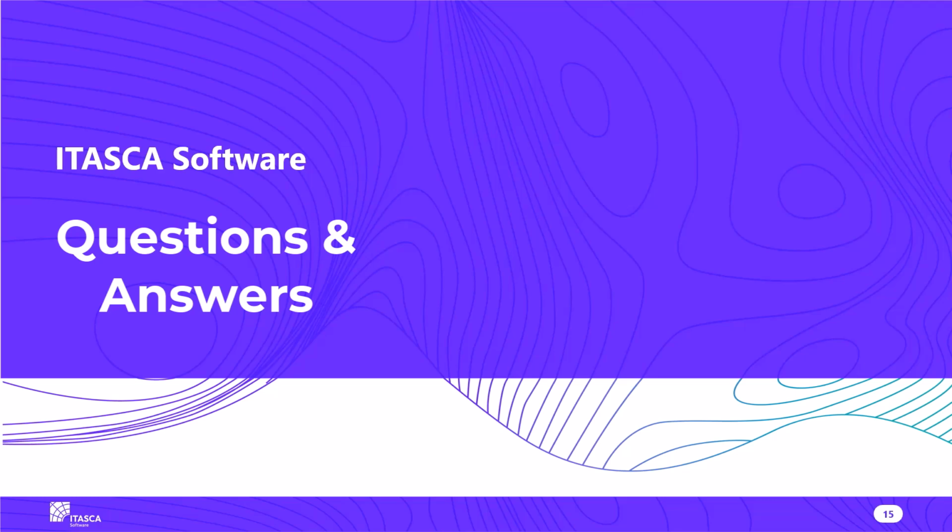I'll take that one. Hoek-Brown does not have to be perfectly plastic. You can have hardening, you can have softening. 50% of that question we can do. It's already built in to allow hardening and softening. In terms of viscoplastic, assuming you mean time-dependent creep type stuff, that is not built in for the Hoek-Brown model. We do have a bunch of different creep models that allow you to do that. As far as I know, none of them are actually based on Hoek-Brown. A couple of them are probably based on Mohr-Coulomb.